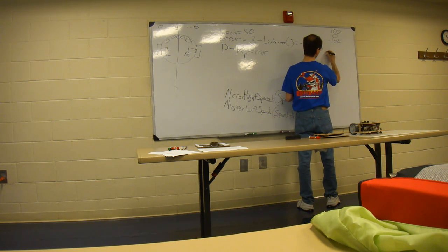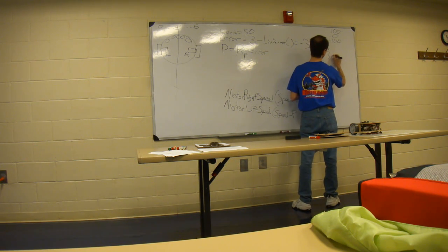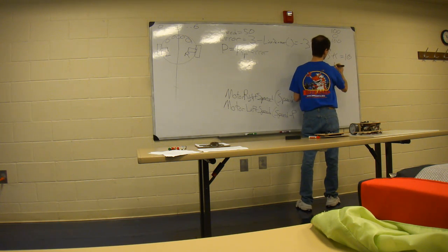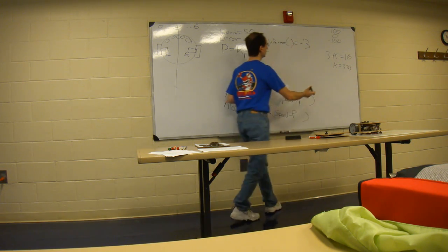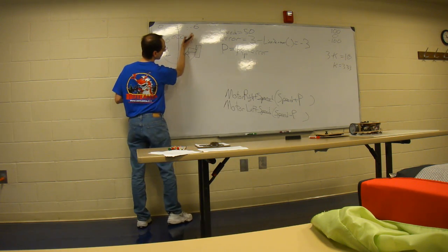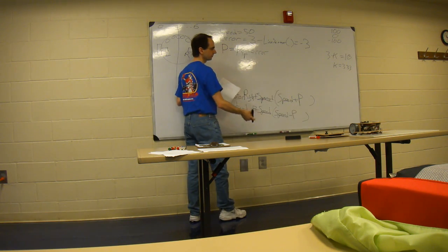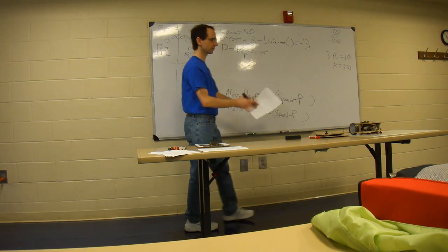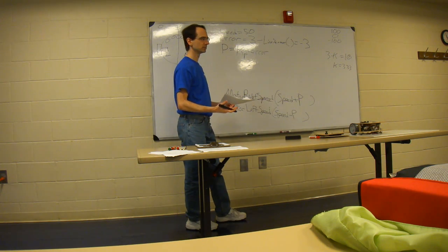So when we're at the maximum error of 3, times the constant equals 10. So we're really looking at a K of 3.33. So now our K is 3.33. When we're at our maximum here, we're outputting 10 and 10 instead of just 3 and 3. So that's just an example. We'd have to actually put it into the robot, try driving it around, and see if that's going to work.